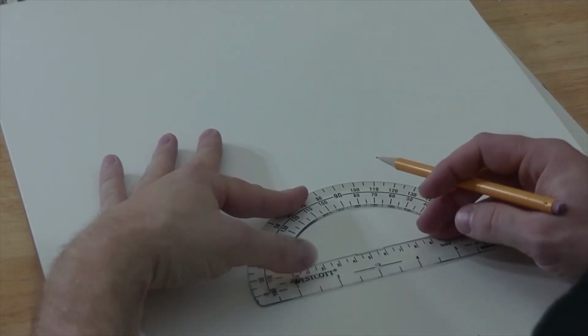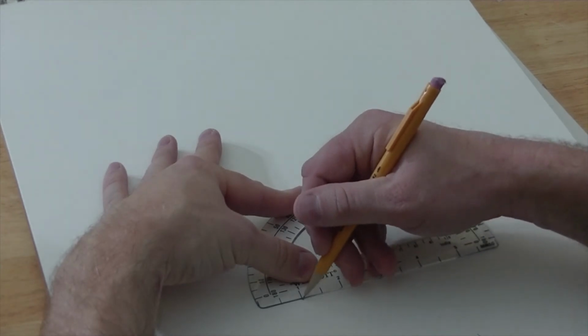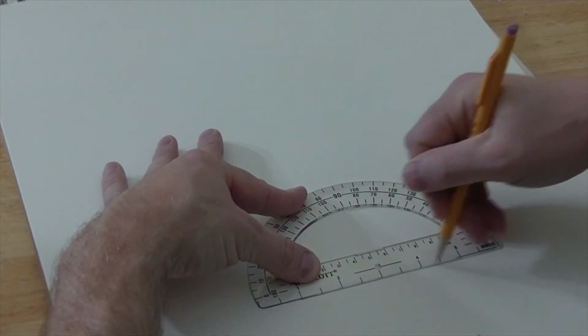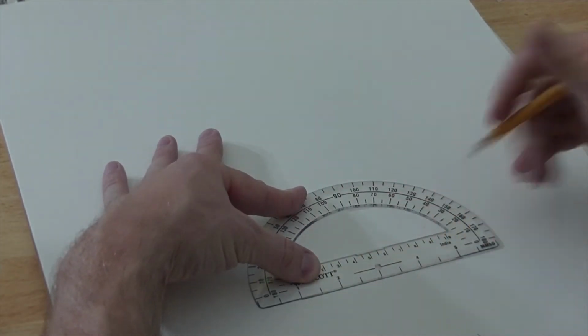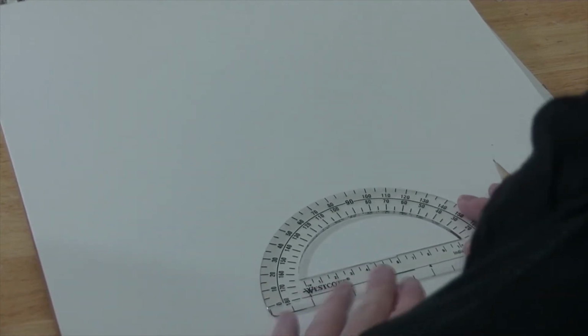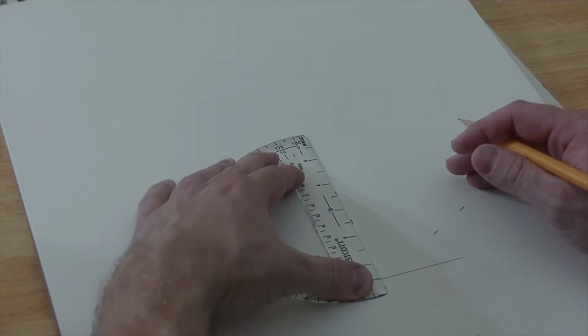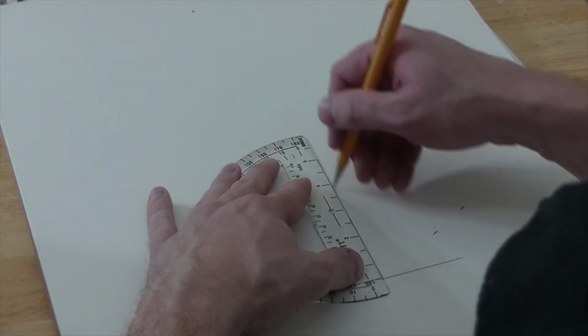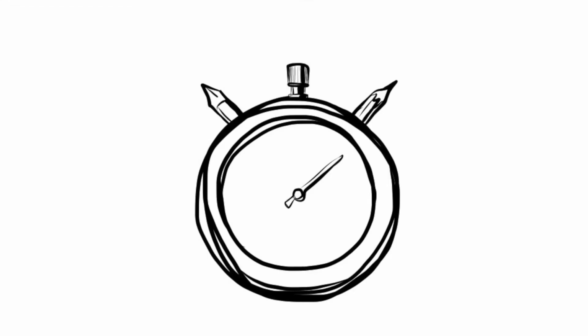First, construct an isometric cube following the steps illustrated in this sequence. Note, be sure all lines of the cube are the same length. First, draw a horizontal baseline at the bottom of the page. Then construct a vertical line in the middle for the front edge of the cube. Okay, start.